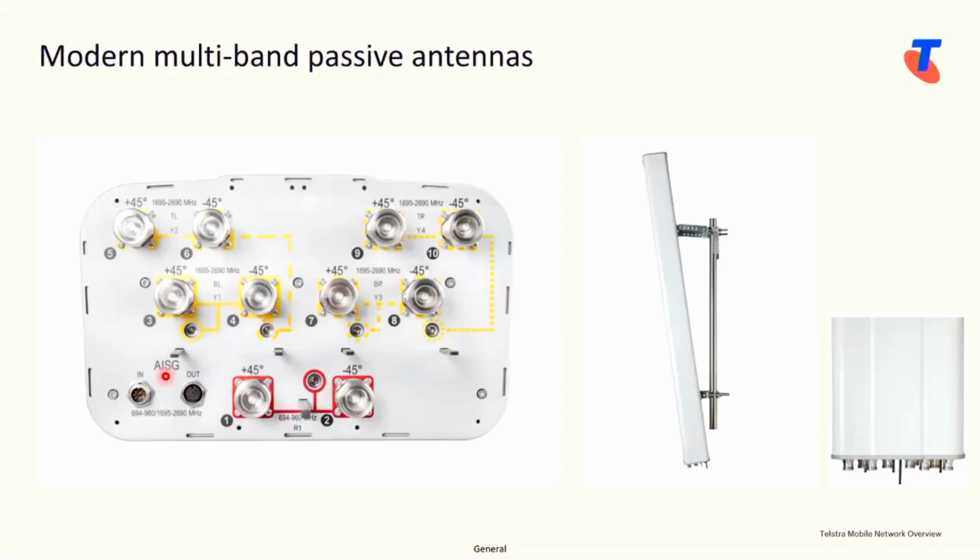You can also change the tilt mechanically, and there's a difference. When you tilt an antenna mechanically, things like the back lobe and side lobes are just getting shifted like this. When you tilt an antenna electrically, it can bring it all down. So it's changing the phasing between the antenna elements inside.